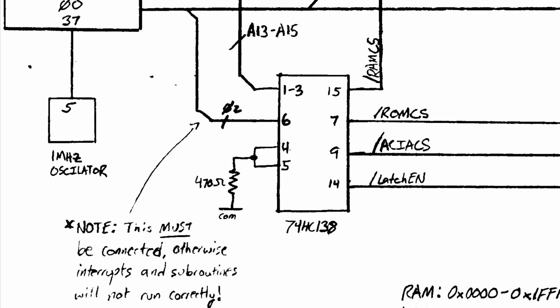Basically, when the processor has the JSR instruction, or jump to subroutine, and it's pushing the high and low bytes onto the stack, there's nothing to disable the RAM between those 2 bytes because the read-write line stays low between both of them, and the address lines stay the same except for decrementing by 1, which means there's nothing to tell the RAM to latch that data in.